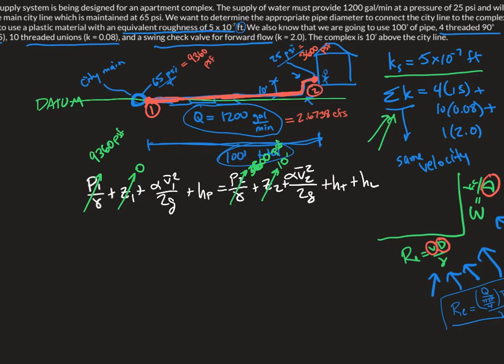The reason that I'm doing that is because I don't want to have to deal with these velocities. So if I do that, then they are the same, right? They have the same velocity. So I don't even need to worry about whether or not they're turbulent or not, although they almost always are. But by putting those points there, by being clever about it, you can save yourself a little bit of hassle.